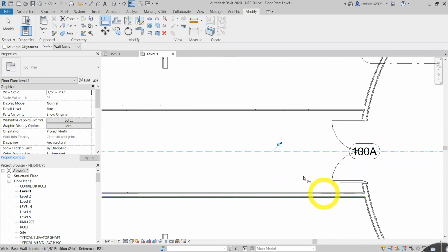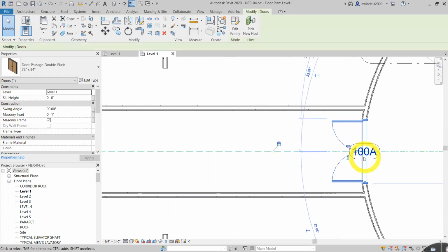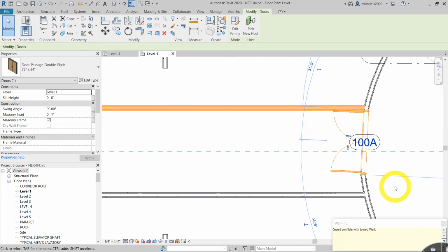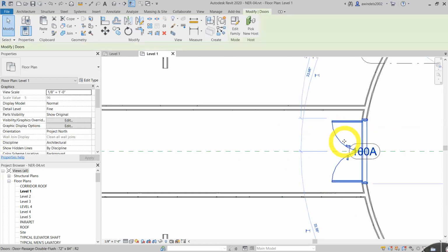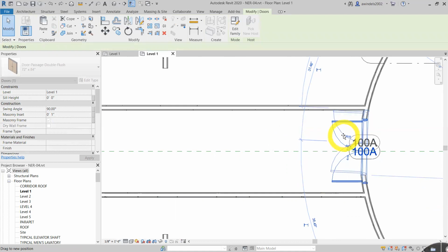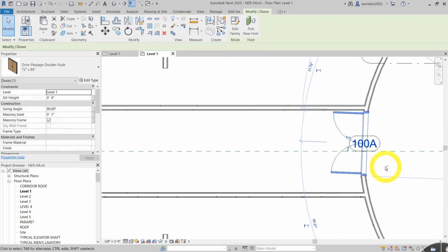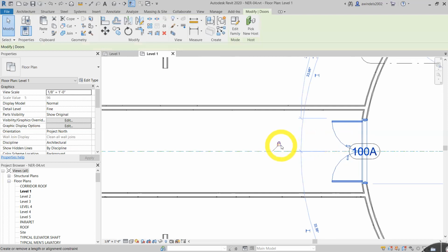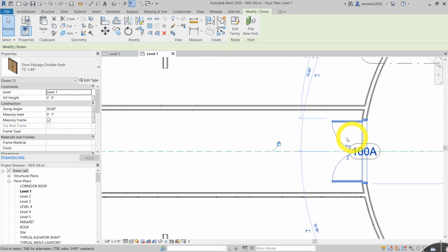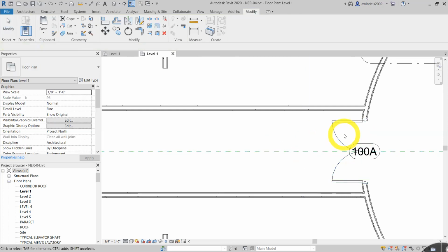And there we go. We can lock it in place as a constraint, so it can't move again. We'll learn more about those later. That's set. So that's what I just did. I locked it. So now I can't move it about. It's warning me it's hitting the wall, but let's move it just a little less, like maybe like that. Now, if I had it locked, which I do now, this blue grip, I can't do that. So constrain as you go.